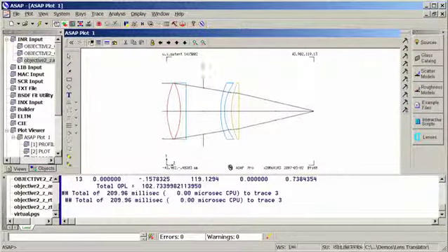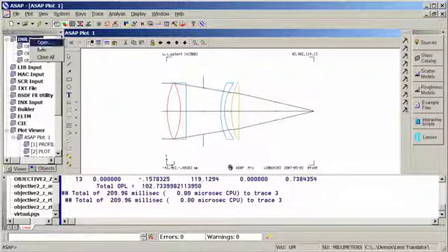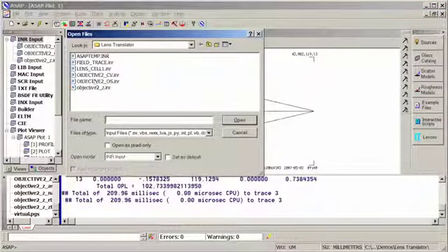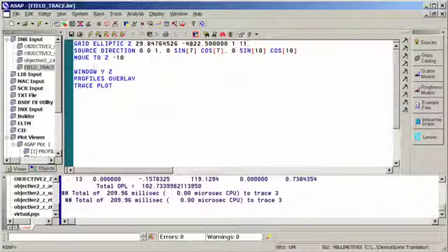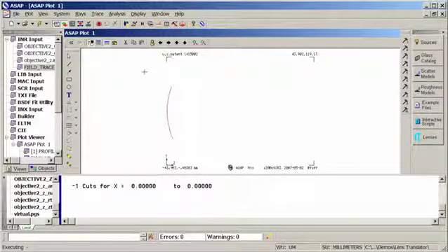And again, here's the system in profile. And again, one of the things I might want to do is to look at rays from all across the field of view. So since this system I know, since I created these files, has a 10-degree field of view, what I'm going to do is trace a set of rays from the on-axis, medial, and the edge of the field. And all I need to do is run this file, and it will trace those rays through that same geometry.